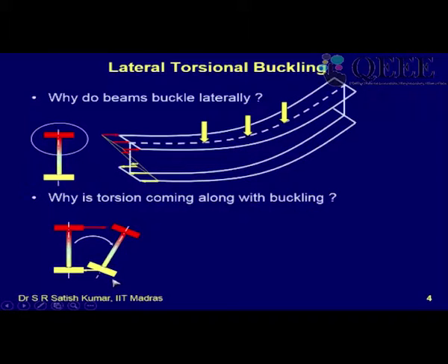Okay. Whereas imagine if I had suspended something from the bottom flange, instead of applying the load on the beam from the top, I hang some load at the bottom. So then my load is downwards here, the resistance is still upwards here. So I have a clockwise restoring moment which will partially compensate for this lateral buckling. So the beam will be able to take a little bit more of the bending, okay, without significant twisting. So the level of load application plays a major role in most problems.